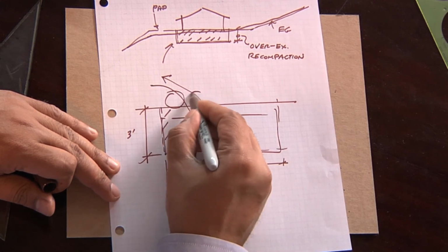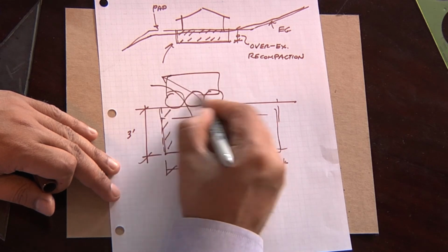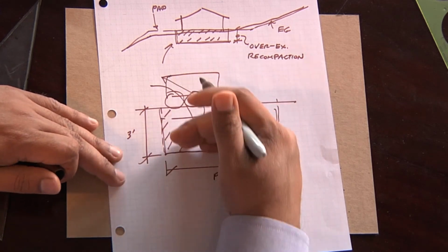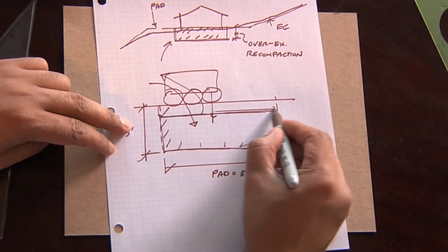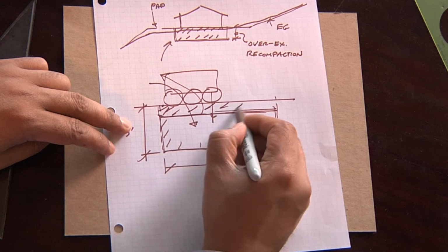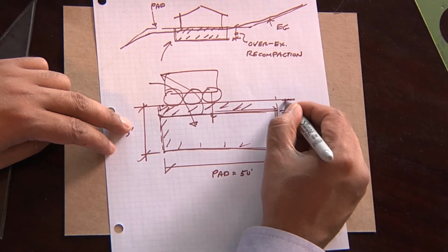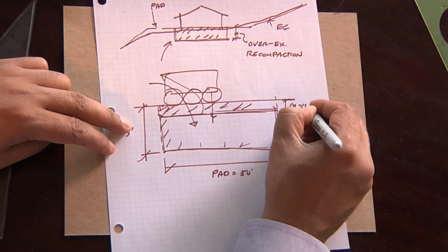That means I run over it with a roller compactor in order to compress it, just like patting it down, pounding it down. When I compact it, it's going to shrink, so I have to have some extra dirt in order to fill up the gap. It's usually going to shrink by 10 to 15%.